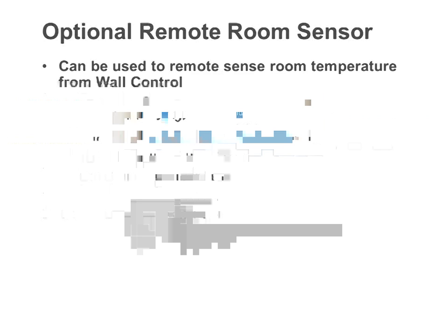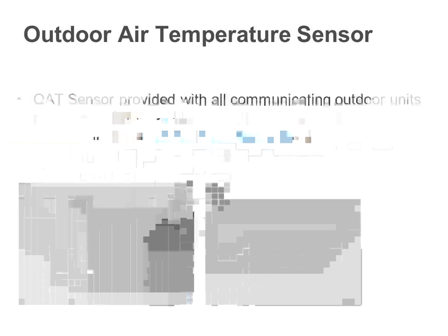The two things you got to pay attention to: one, if the condensing unit is located in a quote-unquote bad location, meaning that the sun is beating down on this thing all the time, you're going to want to relocate that sensor, right? Put it on the other side of the condensing unit, put it on the other side of the house, ideally the north side if you could, and get it out of the direct sunlight so you don't have false readings all day long.